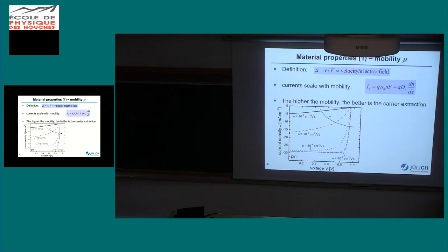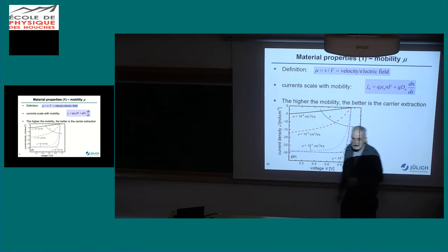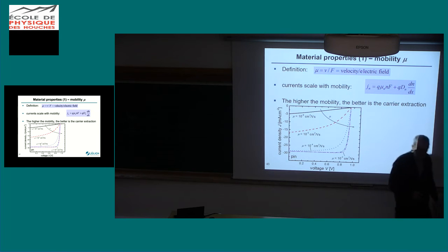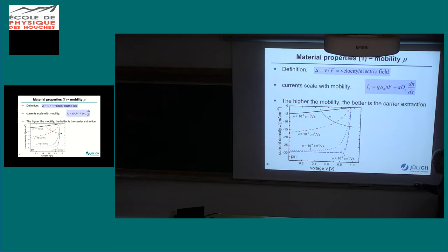But then all of a sudden, and that's all the bullshit that enters in the fill factor, you see it, you go to 10 to the minus 4: JSC unchanged, VOC unchanged, but the maximum power is much lower, and as JSC and VOC are unchanged, the only thing that changes is the fill factor.